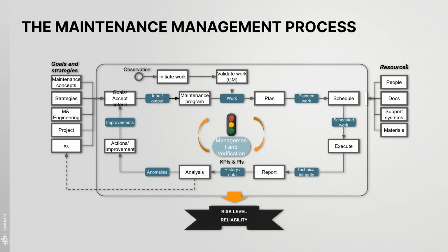This means, for example, optimizing existing strategies and changing the maintenance intervals using data and domain expertise, or moving from corrective maintenance like run to failure to preventive maintenance strategies like maintenance based on running hours, calendar-based inspection, or condition monitoring. So condition monitoring traditionally consists of vibration monitoring, oil or lubricant analysis, motor current signature analysis, etc. And for high voltage machines, it's about partial discharge monitoring